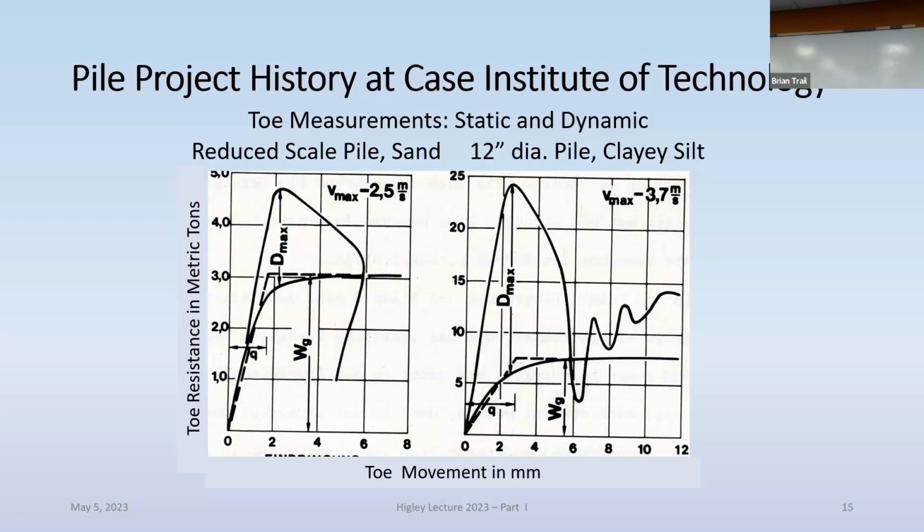And Garland Likins, he did a lot of very good work, actually preparing a table based on soil type that gave us the different case damping factors, which varied between 0.1 for a sand and 1.0 for a clay, for example.